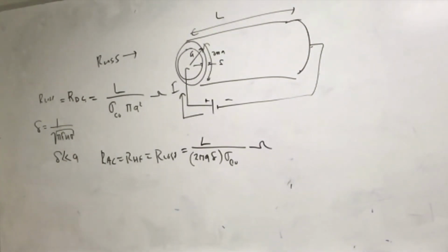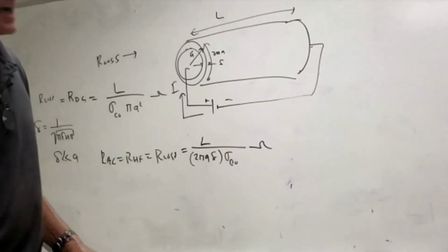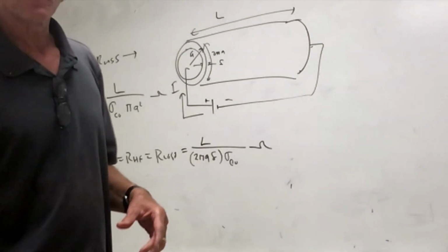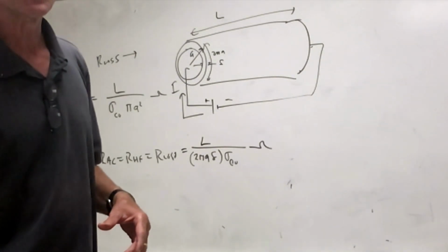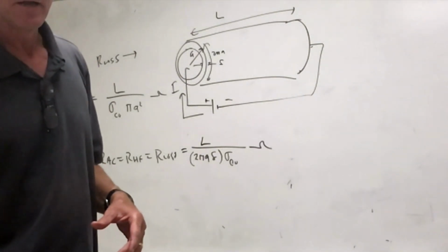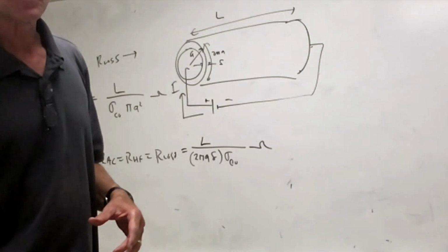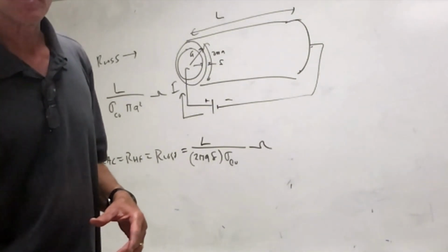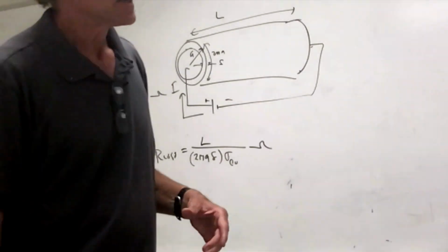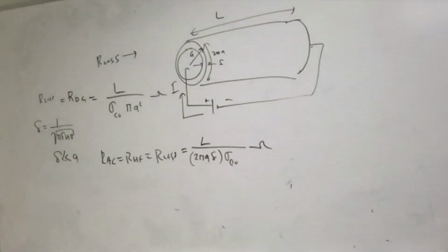But if you have that inductance, you could calculate the impedance. It would be j omega L, if you could figure out the L of that little segment. Do you all agree? And in fact, you can. It's not usually relevant to do it here, because the things that usually limit current in a short dipole are external. There are other things that are going to be dominant. Okay, we've got power rating, and all the things for this short dipole.